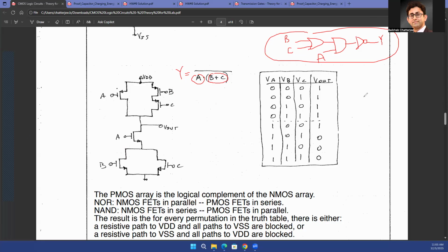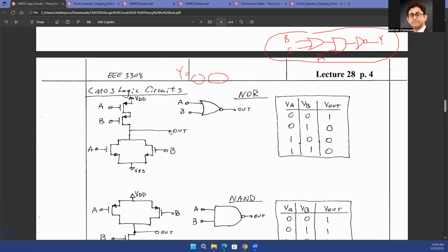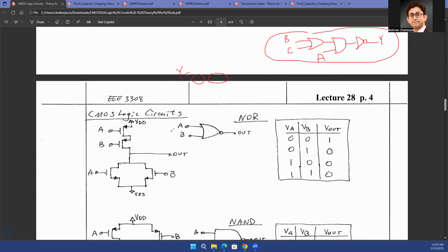How many transistors do you need to create an OR gate? We have just created an OR gate a little while ago, right? So you have created an OR gate, which required 4 transistors. And then if you want an OR gate, not a negative OR gate, you need to invert this output. So 4 plus 2 transistors for an inverter, 6. So just for the OR gate, you need 6 transistors.